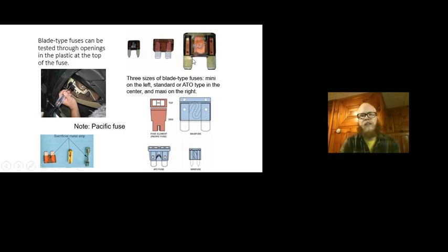So these maxi fuses aren't seen that often anymore. We tend to be between these two. These are the minis, and these are just like the regular blade style fuses. And these specific fuses have become more and more popular as well. You can't test these with a test light, but there's a window on the top, and you can actually look down and see, without having to remove the fuse from the panel, that the fuse has been melted and is open. Sometimes a flashlight comes in handy when we come to that, or your cell phone light, I guess, because that seems to be what everybody likes to use.